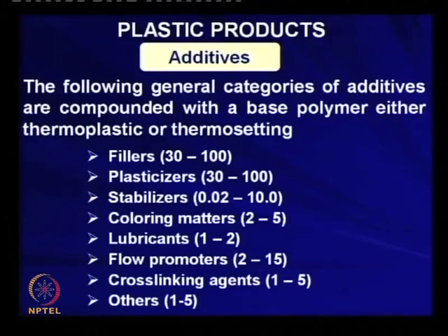That means one kind of filler can reinforce the properties, another kind remains simply inert, present as inert material in the base polymer only to increase the volume of the product, thereby reducing the cost. So, this is the purpose of using filler. Then we can decide what kind of filler we should select and what amount we should use.